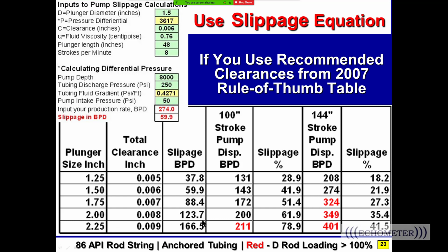So can you imagine going into your boss's office and saying, hey boss, I just ran this brand new pump, I did a great job, and I designed the sucker rod pump clearance based on this paper published by Echometer in 2007, this paper right here. And it says that we are only supposed to get 21% of our new pump displacement. And I think that would be terrible. So that's kind of why I wrote the paper and said use the equation, design your displacement for your conditions in your well, and include your slippage in your calculations.